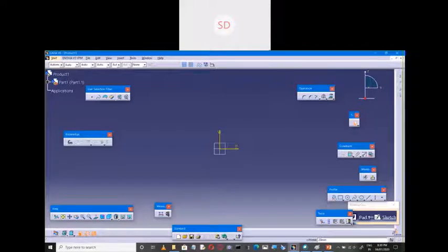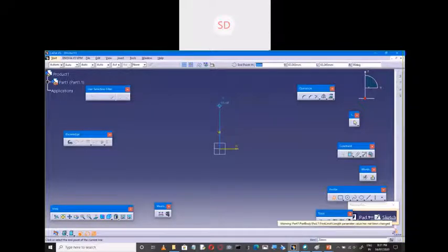Now double click on this profile's continuous segment. Use the tab key: 0, vertical is 100. Now you need to provide the angle here. You can provide the angle as 90 degrees because it is vertical. Let's look at the bottom side: 100. Now from this line, I'll go for 12 mm, length here, and okay.